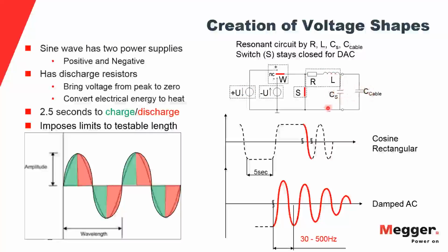We have exactly 2.5 seconds to bring the cable from 0 voltage to maximum, and exactly 2.5 seconds to go from maximum back to 0 to discharge that. So depending on the power that we have available in our power supplies, we have limits to our testable length.